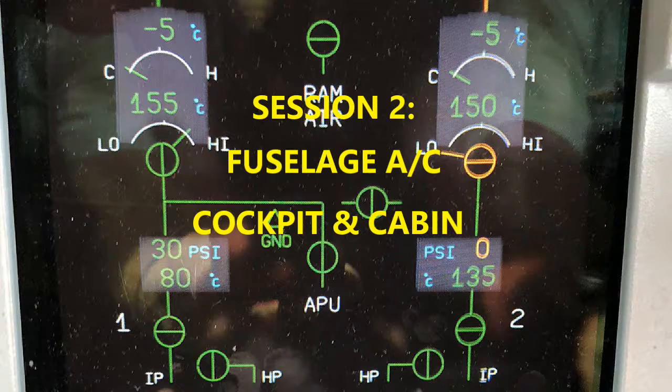So here, what can you expect? The duration of the power-up test in this particular case is 1 second. And during that time, remember what I said, it's going to be checking hardware and software just like in the zone controller. So it's going to initialize all of that. Okay, so let's say the test passes, everything's fine. Then the press page is going to show a normal display. If there's something wrong, then the warnings are going to be in that upper part of the ECAM and, you know, whatever indications there as far as the faults.